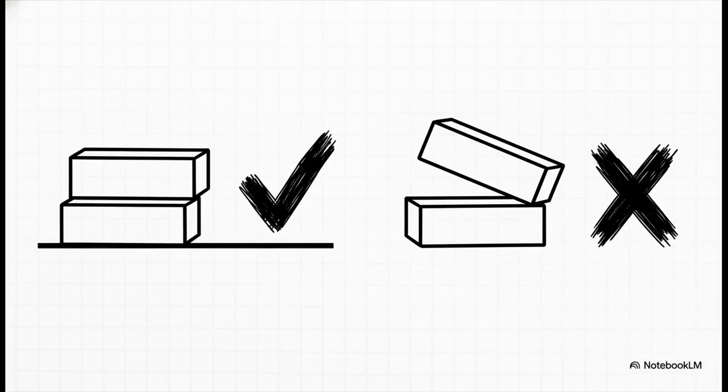So if you remember only one thing from today's explainer, make it your golden rule. Orientation matters just as much as form. You can manufacture a shape to total perfection, but if it's tilted the wrong way, your assembly will fail. Parallelism is your most essential tool for ensuring those parallel assemblies mate together smoothly because it locks a feature's orientation strictly to a functional datum at exactly 0 degrees.